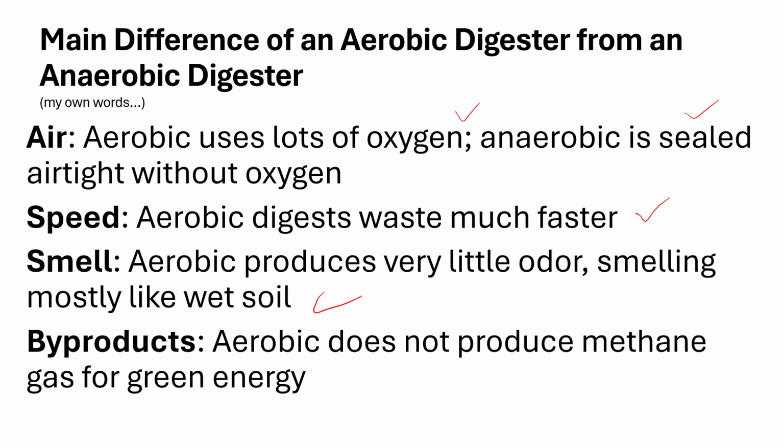That's an open tank. And if you have that upset happening and hydrogen sulfide's produced and there are homes or businesses or even highways nearby, you are going to hear about it very quick. And basically with respect to that, you'll dose it with calcium carbonate, lime. I've also seen people dose it with freeze-dried microbes that are gathered and freeze-dried, and they're predators to go after the bacteria that produce the enzymes that are creating hydrogen sulfide gas.